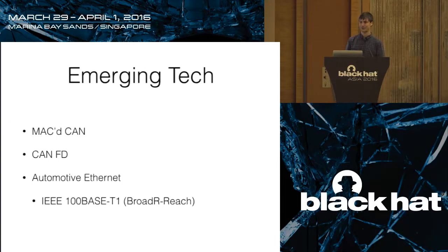Other problems with this is you need to be able to do it quickly. I mean, these systems are real-time systems. If you introduce latency of doing verifications, that can totally destroy the system in some cases. There are real hard timing requirements. And if you don't get something in the right rate, often what cars will do is they'll go into an open loop control mode. I don't know if anyone's had a car go into limp home mode, but basically you can't get above 2,000 RPM. And if you're on the highway and that happens, it's kind of annoying. You basically put your foot to the floor and pull off the highway. Those types of things, they can't be happening on a day-to-day basis.